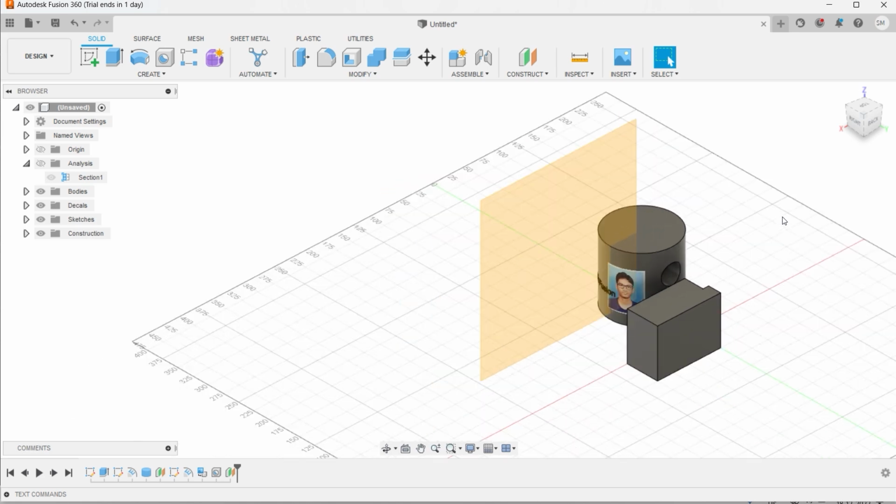Okay, now excluding this one, we want to show little bit of assemblies also here. So the assembly in Autodesk Fusion 360 is little bit different compared to the normal softwares. Actually, whatever we are following in SolidWorks, this is completely different. In these cases, we need not follow 3 different constraints. In these cases, we need to bring the different parts together, and with these parts, we need to assign some different types of joints, right?